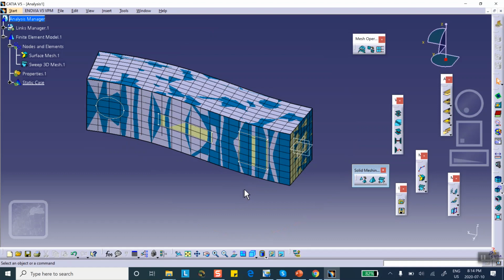in the next video segment, notice that sweep requires a volume because you're going to be sweeping along that volume. The next video segment, there is no volume. There is no basically geometry. Here I have a geometry that I'm using for sweeping purposes, okay? In the next video segment, you have basically an orphan mesh. You create an orphan mesh. There is no geometry associated with it, and there's some subtle differences between those and the problem that we're doing